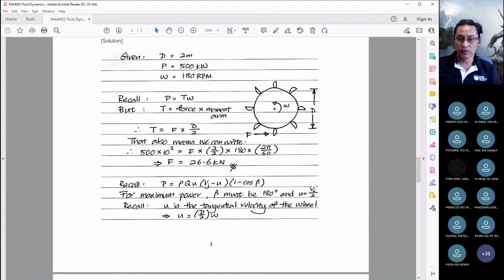We know that for maximum power, beta must be equal to 180 degrees, and U must be equal to half of the jet velocity. All this stuff we've covered in our recorded lecture previously. So if you have no idea what I'm talking about, please go back and watch those lectures.